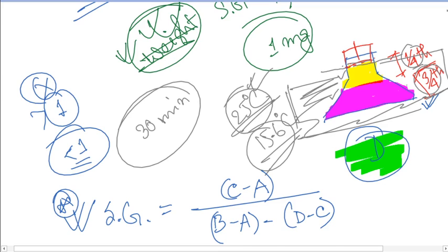To remove any adverse effect of this, we are taking a smaller amount of water, so that water will always stay above and not penetrate beneath the sample and mislead us from the original value of specific gravity. So this is the main reason. There might be other reasons as well. According to my understanding, that's why we are using 3/4, not less than half of the original volume. Keeping a safe margin, we assume at least 3/4, so that it will not create any problem.